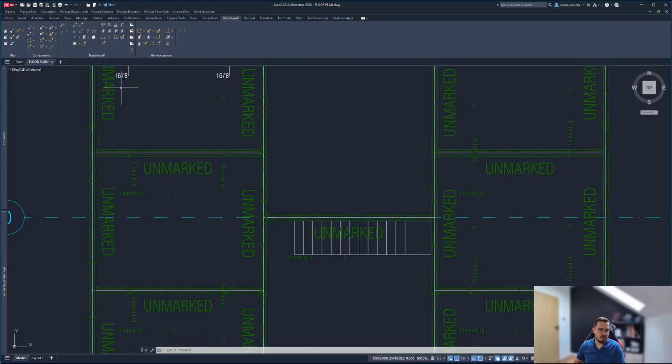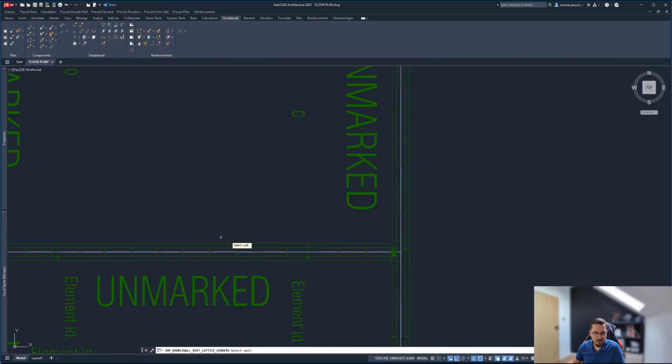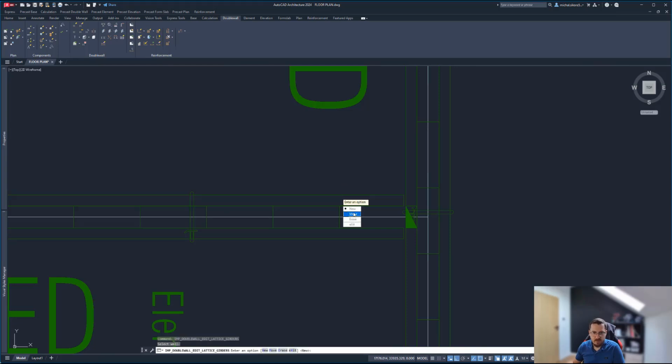Before we move further, let's see how to move the girders about. In order to do that, I can click on this tool and select a wall. For example, let me select this one, and I can move a girder space to a previous or next location. But you see, it gets marked red once I move it, because it has been placed in that nice sweet spot between the minimum and maximum distance from the edge of the level wall. With this option, I'm moving it by 300 mil, which is the spacing of the girders that we have, and we're moving it too close, so we don't really need to change the position of that. But if need be, of course you can.